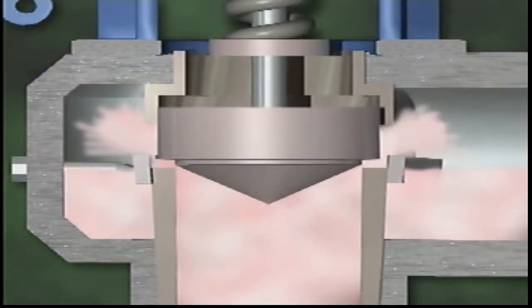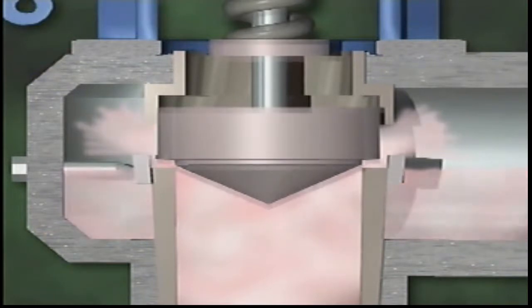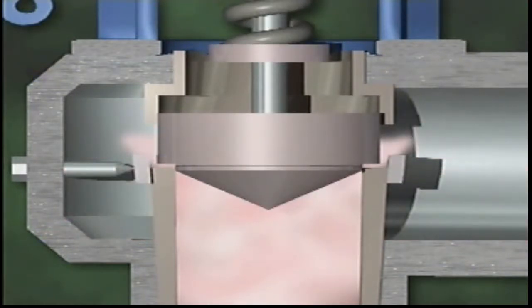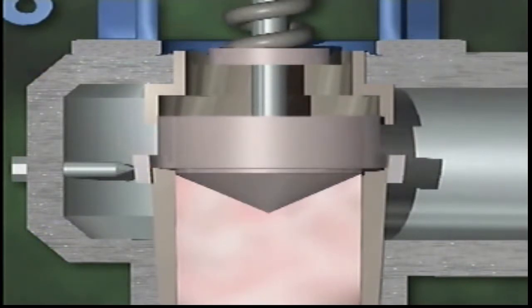As pressure decreases, the velocity of the escaping fluid also decreases. Spring tension begins to take over, pushing the disc down. The spring tension in a safety valve is preset, and it must be correct for the valve to operate properly. When the system pressure drops to the point where the valve popped open, 1,000 psi in this case, the valve doesn't close, because the lip of the disc is still exposed to the pressure and velocity of the escaping fluid. When the system pressure drops to a predetermined value below the valve's popping pressure, the disc drops down on the seat, closing the valve.